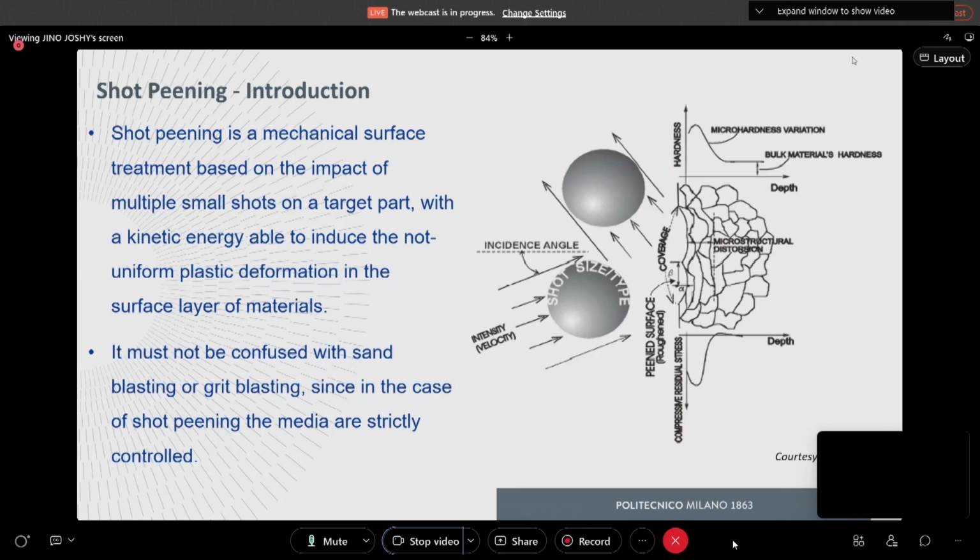There is this effect that is the formation of the grains of the microstructure with the introduction of hardening, and this is also seen here in this graph. It refers to the trend of the hardness in depth, and we see that after a short period, the hardness is increased with respect to the core, with a characteristic trend. Then the trend can be with a peak just under the surface,